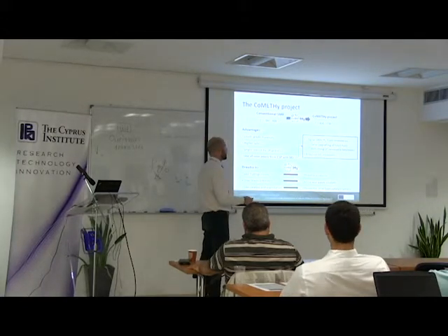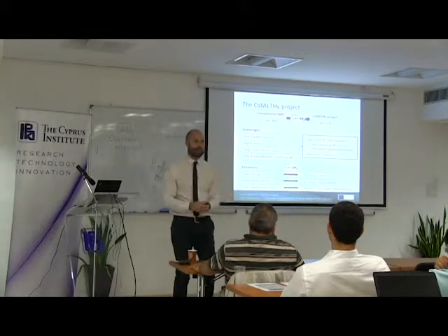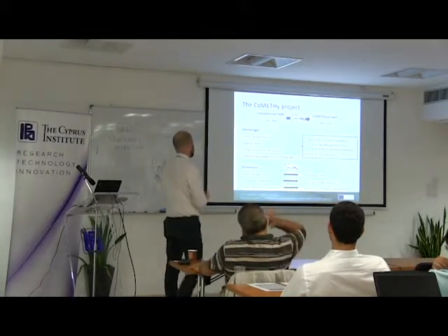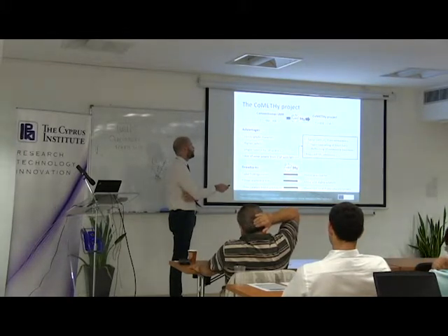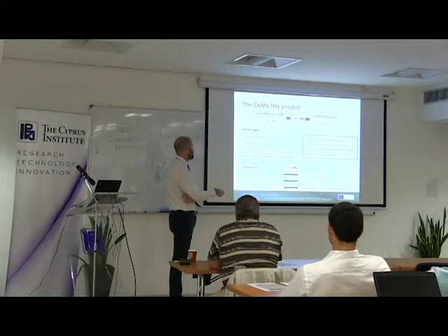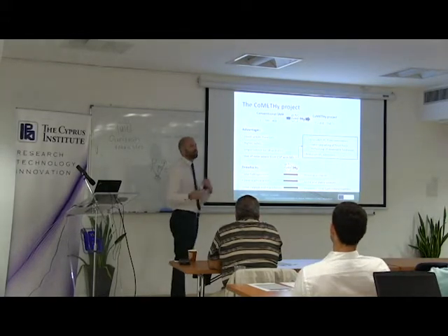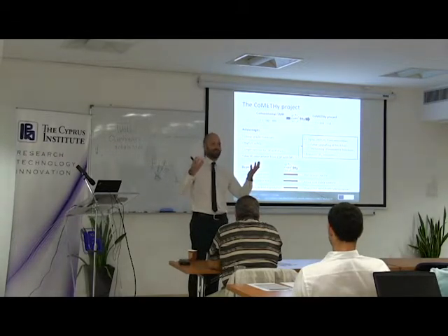Or in any case, you can reduce CO2 emissions and you can very much facilitate CO2 capture with this process. What are the problems? Why don't we usually do steam reforming at this temperature? It is a strongly endothermic reaction, which means that it wants to operate at high temperature.